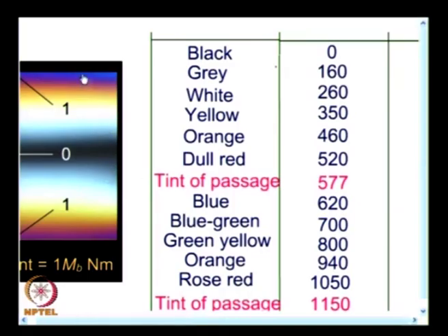And you will also notice, this is the top portion of the beam which is subjected to compression, and the bottom portion of the beam which is subjected to tension, and because of the Poisson effect you see a slight change in color. If I look at it with black and white, you may not notice this color change so well, and this is also a magnified picture.